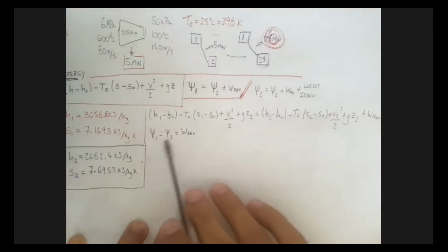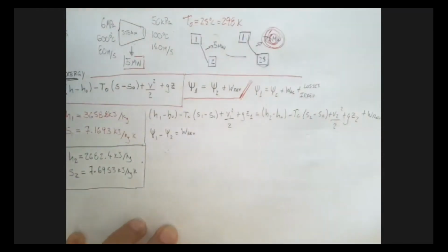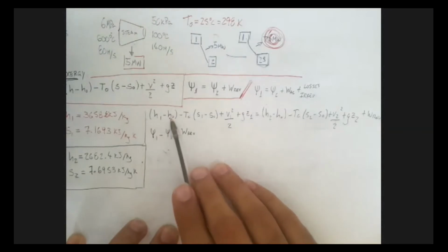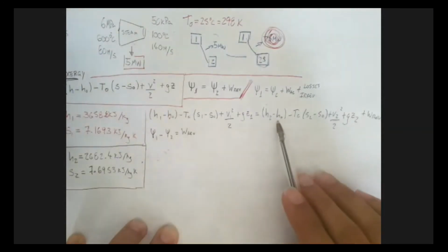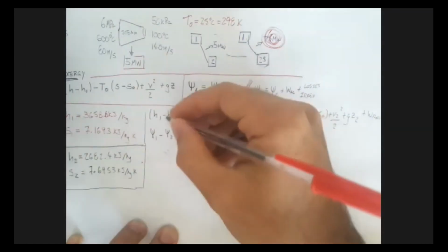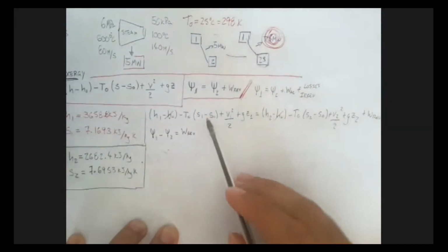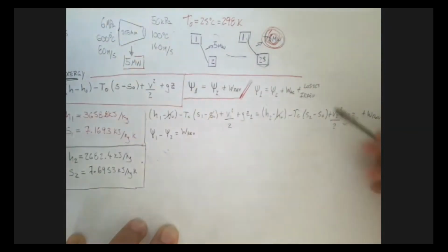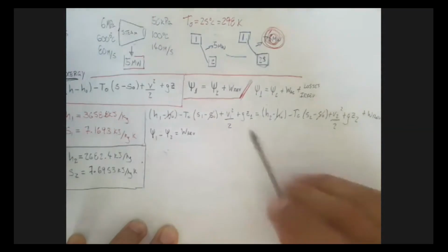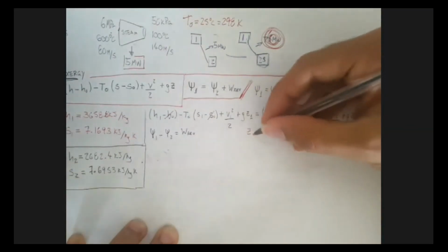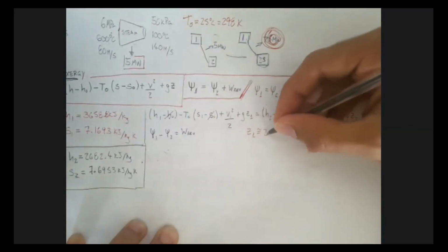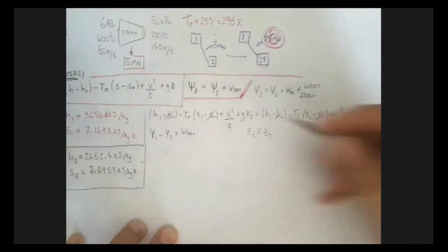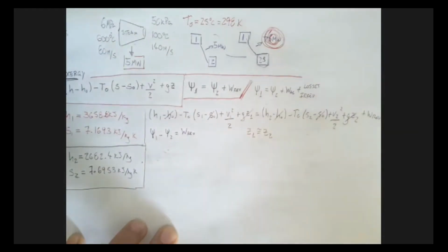Yeah? So what I can do is I can subtract these two monsters here. And then check it out what happens. We have a negative enthalpy naught, and then this is going to be a positive enthalpy naught. This goes away. We have a positive entropy naught, and we have a negative entropy naught over here. It goes away. Then, as long as my heights are similar, and we talked about this before, right? As long as this turbine is not ginormous, these guys are going to be the same. We can eliminate them. Don't have to account for them.